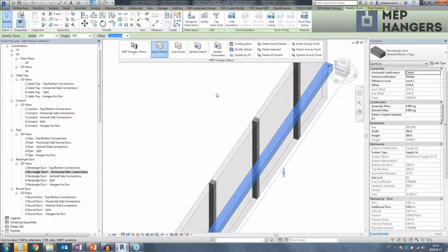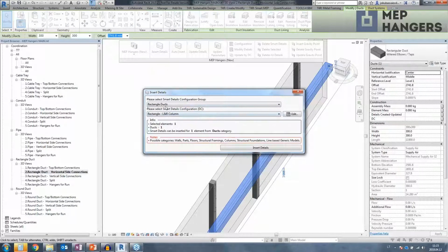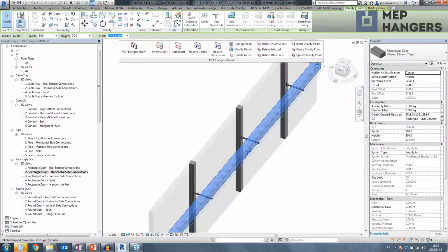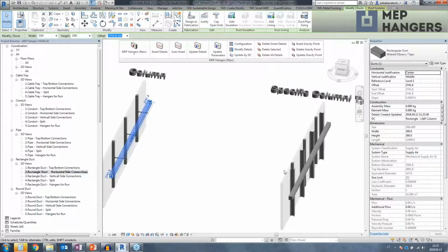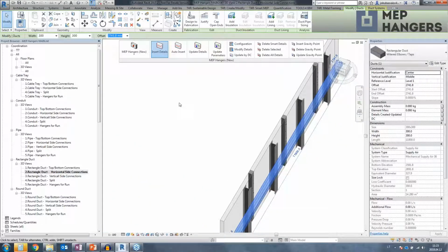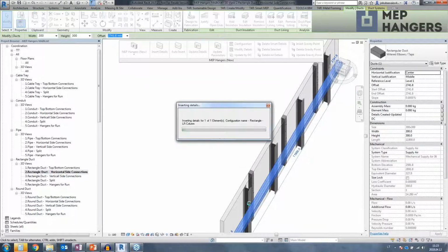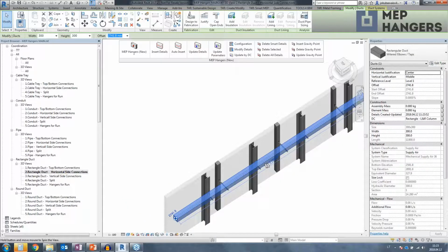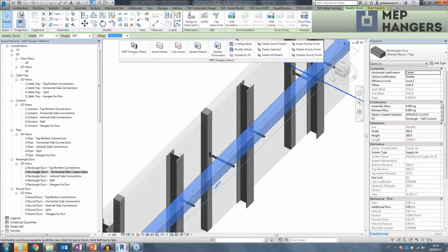The same is here when we are speaking about the columns. So we just go with the same configuration, just looking for the column. It is trying to stretch the family up to the column. For example, in this situation, we have two different columns. If I run the same configuration as the previous one, it's going to connect to one and to another column immediately, and the distances of those structural frames are changing.